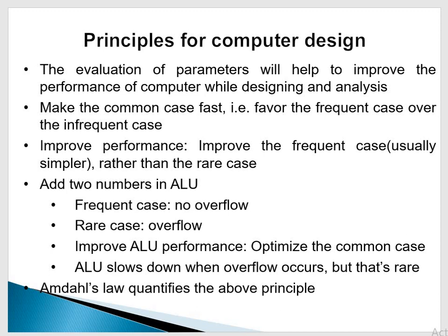For example, let's suppose we are going to add two signed numbers, and both numbers are positive, and after the execution, if the MSB becomes 1 due to the values of these two numbers, then the overflow flag will have to be set, which will indicate that your sign has changed. We were expecting a positive result, but we are getting a negative number. So now why are we calling the overflow flag being set a rare case?